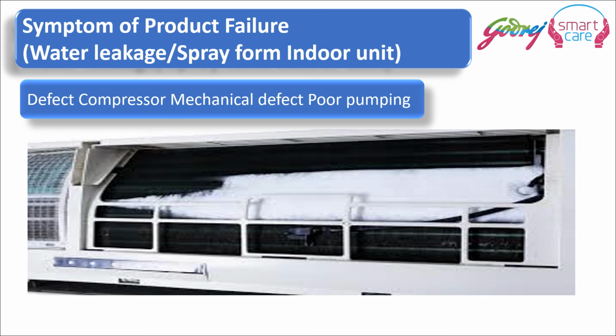For poor pumping of the compressor: if the compressor is not pumping properly or if there is any mechanical defect in the compressor, sometimes in rare cases ice formation is found on the indoor unit, and this ice will immediately melt and form droplets. These droplets are more than the drain can handle and they can fall from all places and create a mess of water dripping from any random place. There is no fixed place from where water can fall in such a condition.